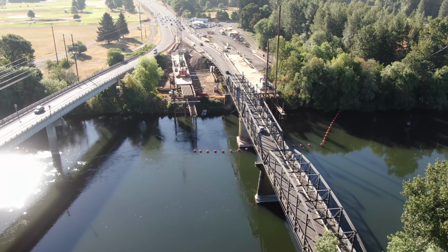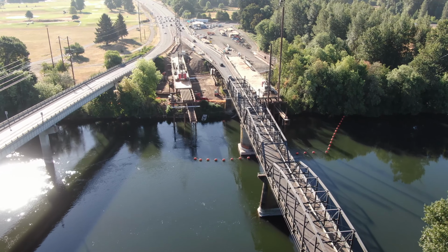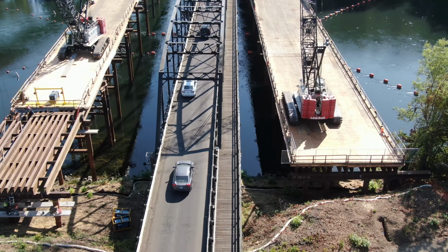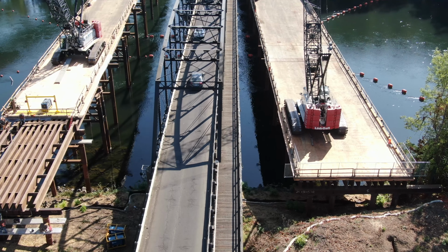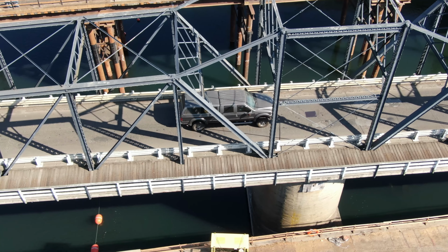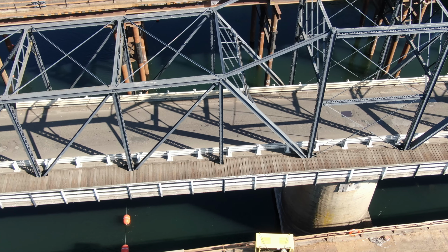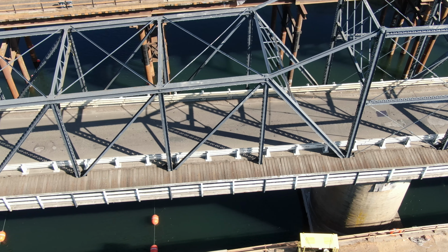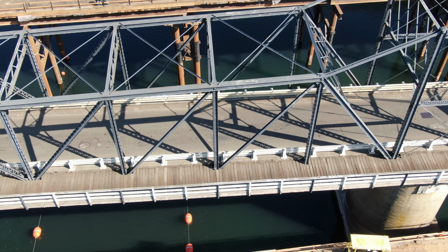Load combinations rationally predict what loads will act together. Engineers then apply load factors to account for uncertainties in the loads, and to emphasize certain types of load cases. Later, in member design, engineers multiply resistance factors by member strength to account for material uncertainties.